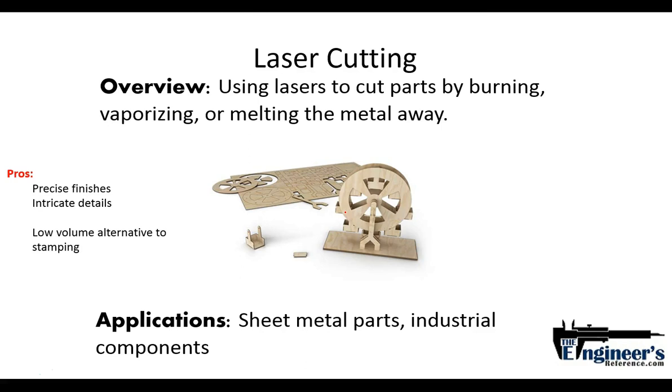Some of the pros: you get precise cutting, you get very intricate details, but it's a low volume alternative to stamping processes. So a lot of stamp and die operations can be an alternative to laser cutting. Some of the cons: you can't really get a lot of 3D parts. There may be some specialization, but that's not typically a laser cutting operation. And you do have some restrictions to part thickness.